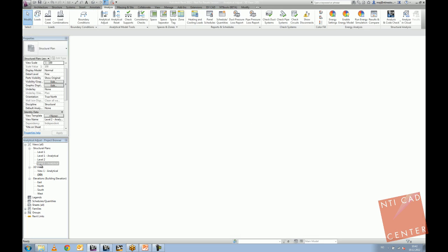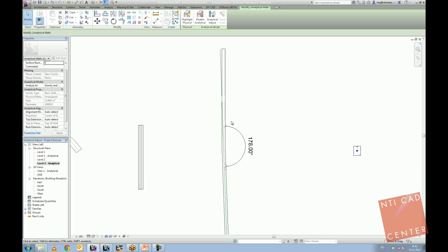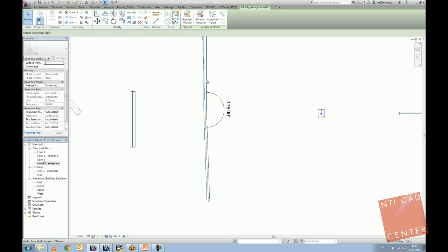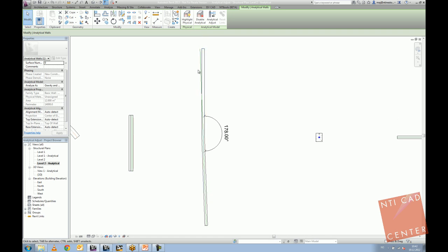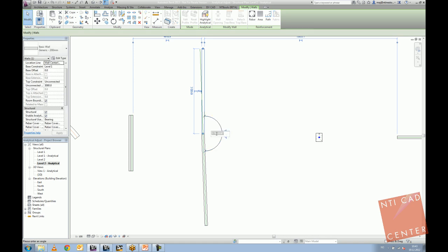A little bit more. For example, with this wall again, you will see the analytical lines. Again, it's something like logic inside of Revit, saying that if the angle between the walls is really small, maybe it's actually wise to maintain the straight line. Maybe it's not important to break it down. So again, if I select this wall and switch to a bigger angle, come on, let's try it a little bit bigger then.